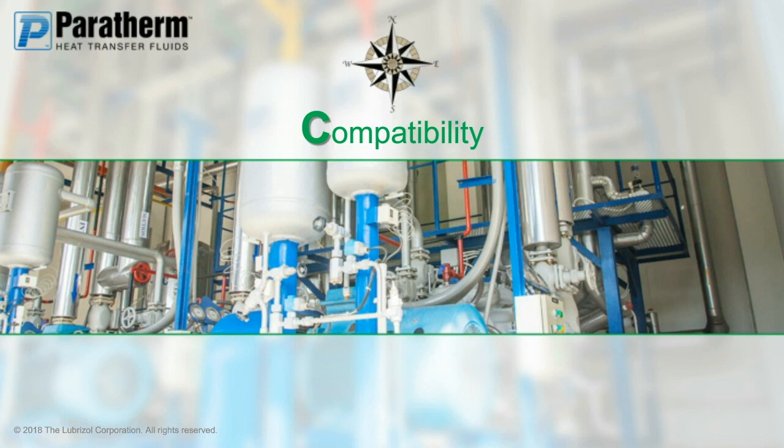But there are specific tests that a fluid supplier will be able to offer, or should be able to offer you, to prove that by mixing one fluid in any ratio with another, you're not going to have any inherent reactivity, or you're not forming something new that's going to be outside of the design specifications of the fluid that you're running. The next issue, contamination.